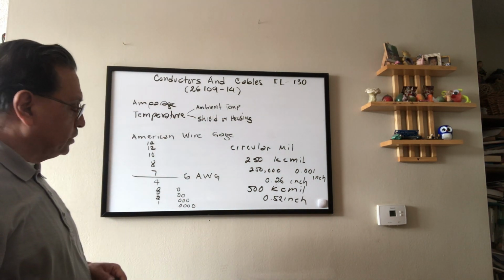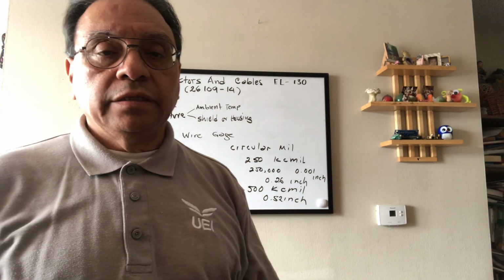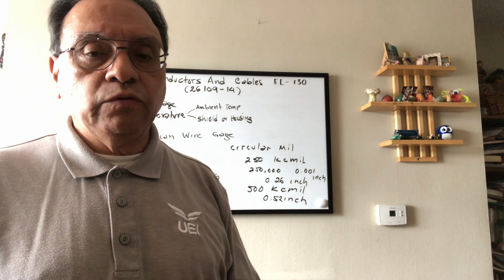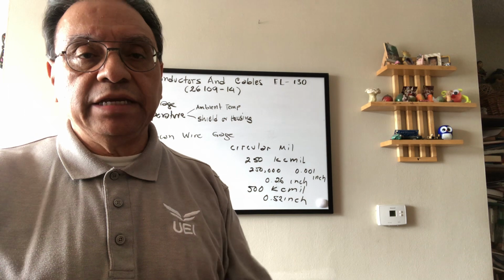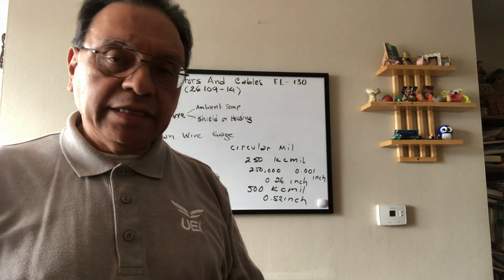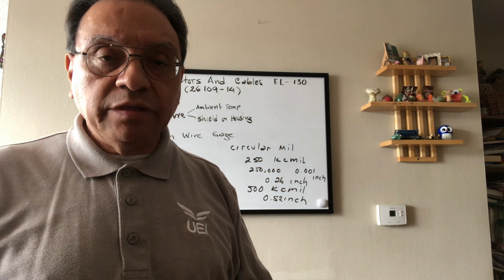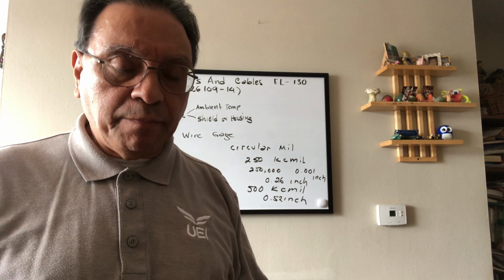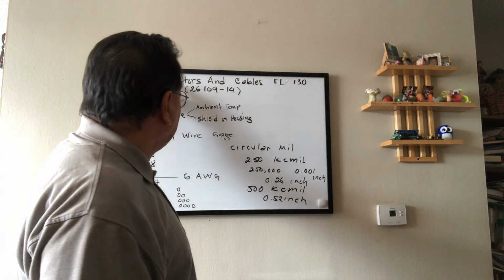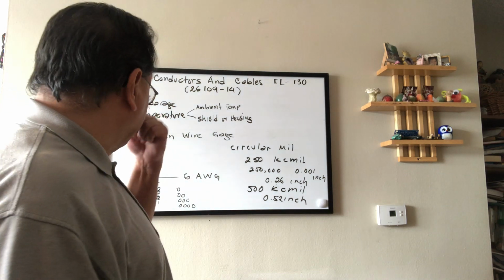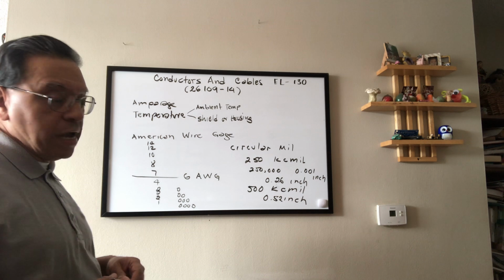So that is the first thing. But one more time, in the previous video we were discussing that the first thing that I do is check the kind of electrical device I need to feed. And the kind and the amount, checking the documentation, I determine the total amount of amperes that I need. I select my protection and I select the electrical conductor. And the electrical conductors are classified based on the American wire gauge.